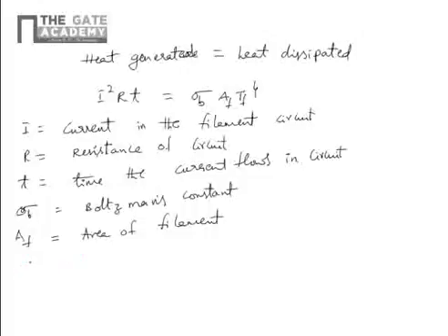Pyrometers measure high temperatures accurately, but at low temperatures there is error. A thermocouple is used for low temperatures.